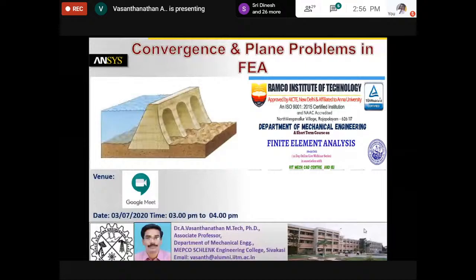So this is my own paper. Okay, so you just see here. I have an experimental result, so you can plot it here. Let's say, for example, this is the experimental result. Then these are the mesh sizes in my analysis. I start with 3.8. Then slowly I am moving from coarse to fine. Okay, so I got a result with the 2 millimeter mesh size. Then I reduce it further to 1.8 or 1.6, something like that.